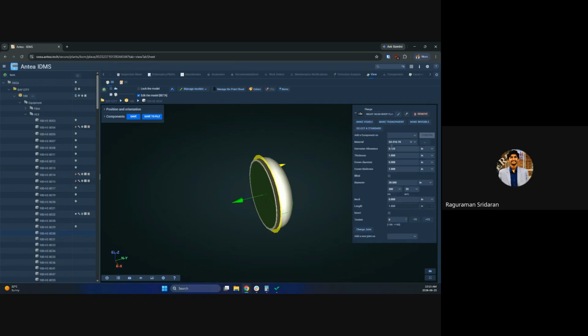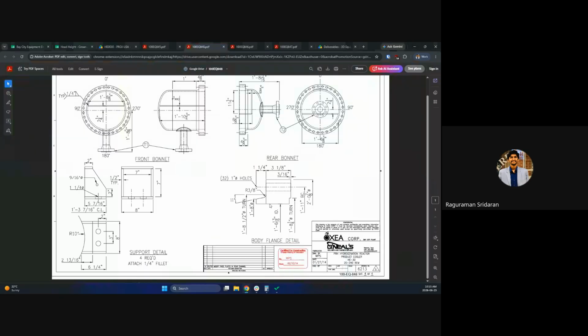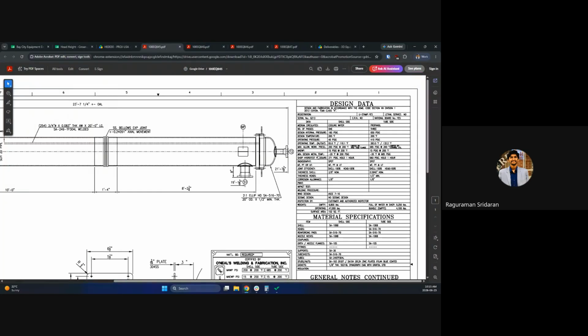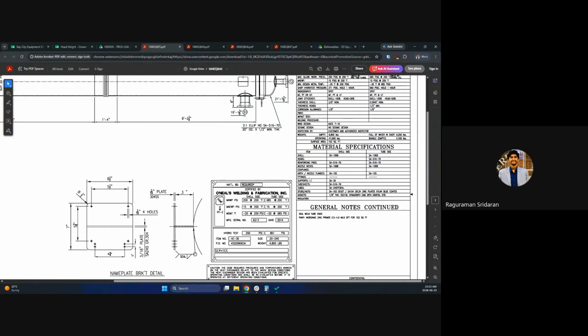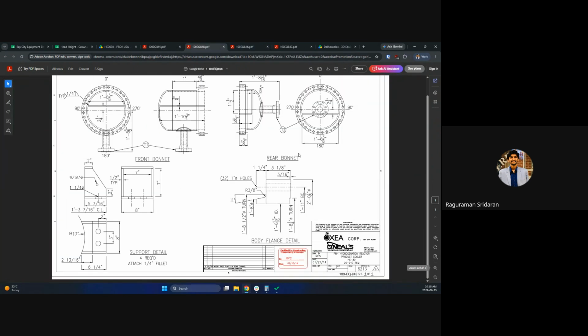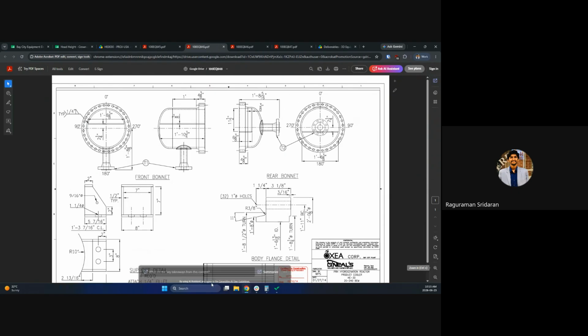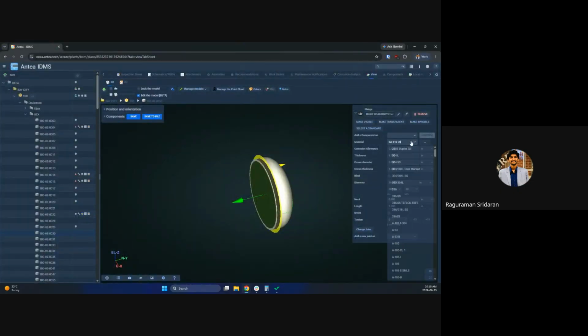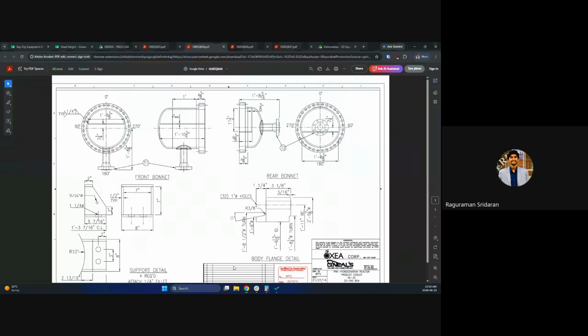So now we come here and we will try to find the material, which says the fittings, nozzles, flanges go with SA105 unless it states different. Okay. Good. You can notice whatever we set here is being populated automatically, but we need to make sure the thickness and the other values are adjusted accordingly.